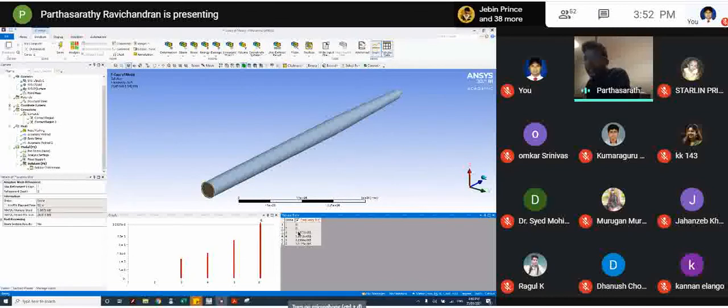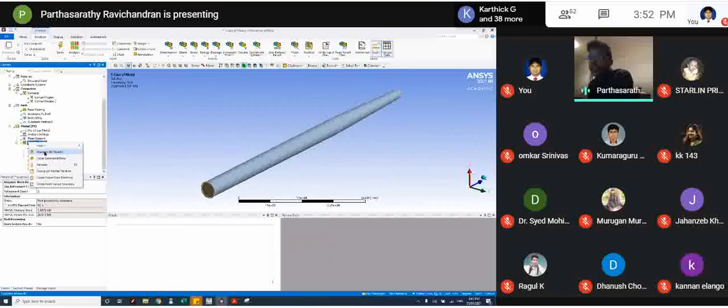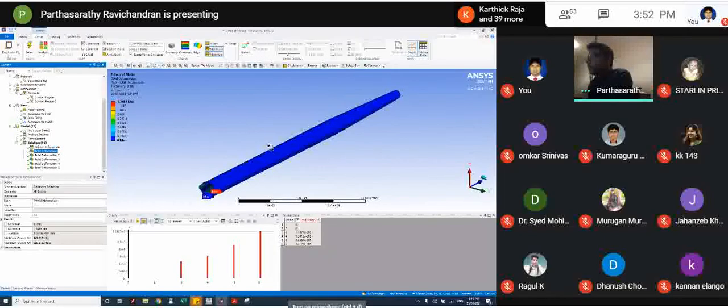It means that what it has done is not properly solved the model, and when you try to get the mode shape results, you won't find the same thing as what you got in the first boundary condition. As I said, the transfer of forces, or the transfer of the top mass to this structure, didn't apply properly. That's why you are seeing this incorrect result.